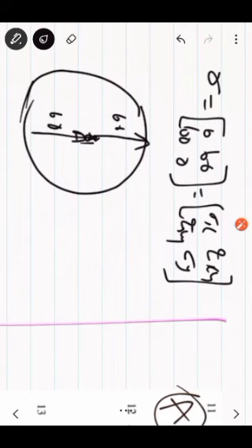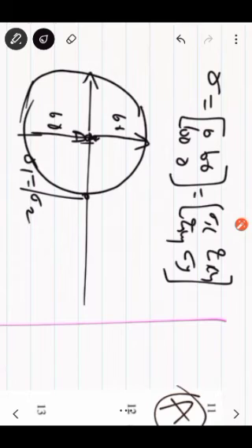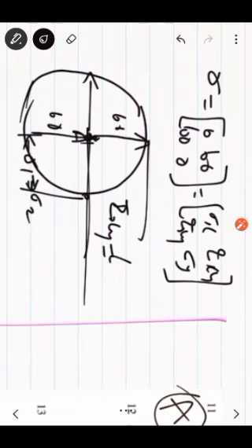You will have the maximum along the x direction. So from A, you measure this is sigma 1, and sigma 2 in this direction. If I take that direction also, from A only you have to measure. From A it is sigma 1, that is equal to this value. Okay, and this is tau xy, so that is equal to 60, this is also equal to 60. So the maximum stress that is acting is this one.